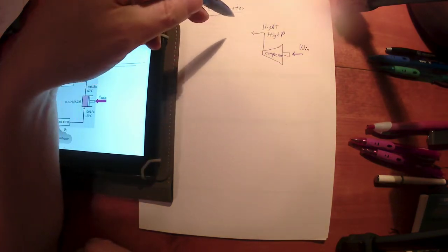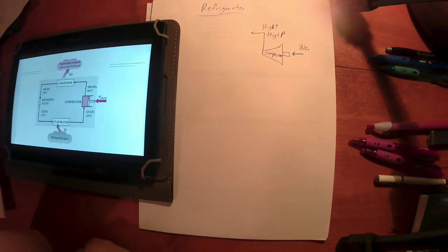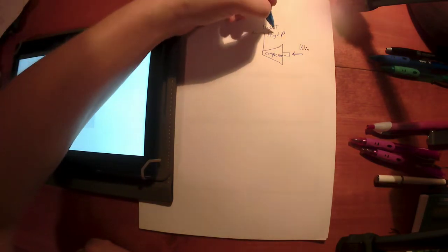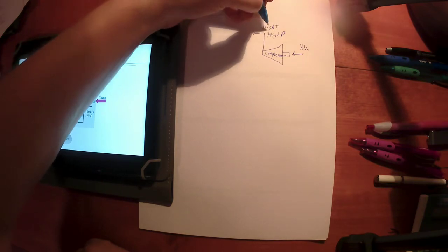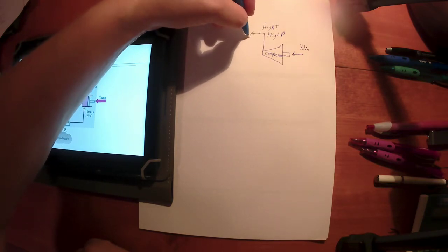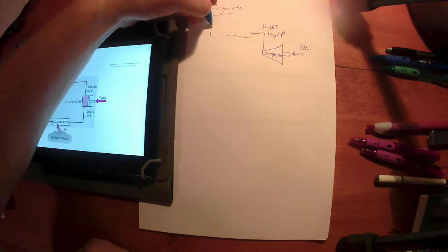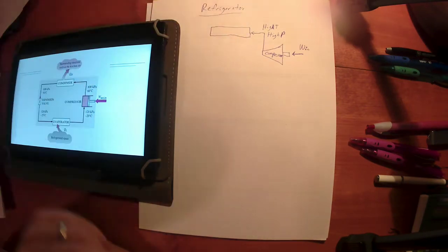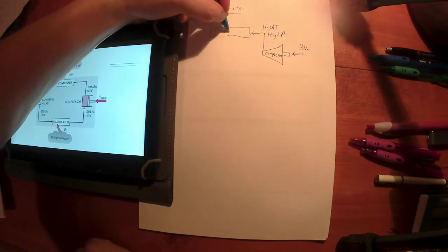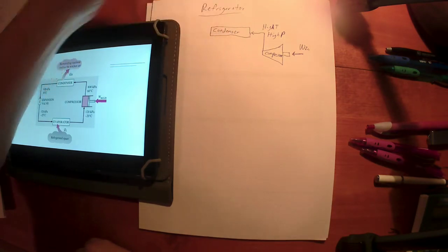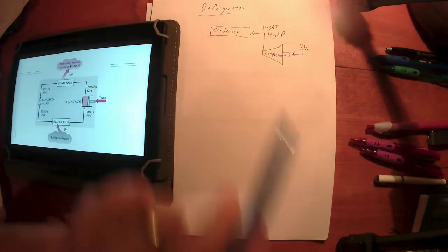And we just talked about when you squeeze a gas, a lot of times the temperature will increase. And this is really kind of what we're after in a refrigerator. We want both the high pressure, but more importantly, we want this high temperature. I like to say we get this refrigerant screaming hot. We get this refrigerant so hot that when we run it through the condenser coils, this is a heat exchanger.